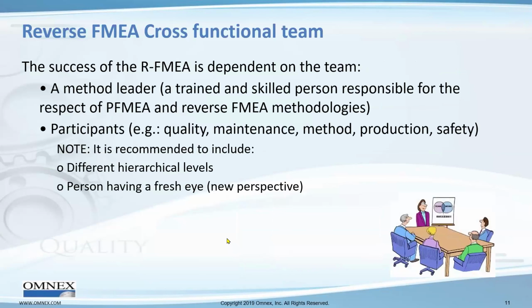So as we look at it, reverse FMEA, and this is common to a lot of the core tools, is that we need a good cross-functional team for a reverse FMEA. This is going to be a lot more focused. You know, if we normally do a PFMEA, this is going to be focused strictly on that operation that we're doing that day.